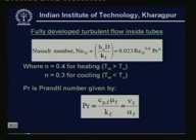So, Prandtl number is Cp mu by K, which can also be written in terms of kinematic viscosity nu divided by the thermal diffusivity alpha. So, Prandtl number is basically nu by alpha, and in this Dittus-Boelter equation, there is another parameter n, and this n will take the value of 0.4 for heating. That means, when the fluid is getting heated, you have to use a value of 0.4 for n, and if the fluid is getting cooled, then you must use a value of 0.3.